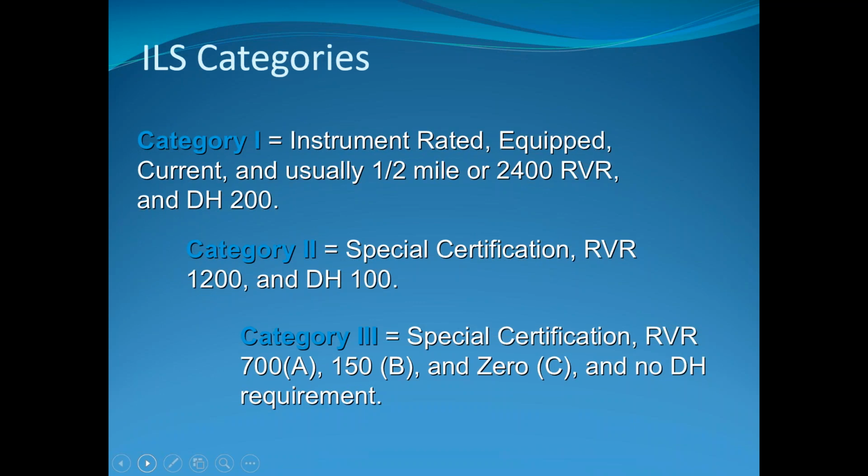But a 747, if it's going down, shooting a really low visibility approach, and it gets down below 300 feet, they say, or sometimes 200 feet, and if they still can't see, they make that decision that they're not going to land, and they do what's called a go around, where they throttle back up and climb back out, and they try again essentially.